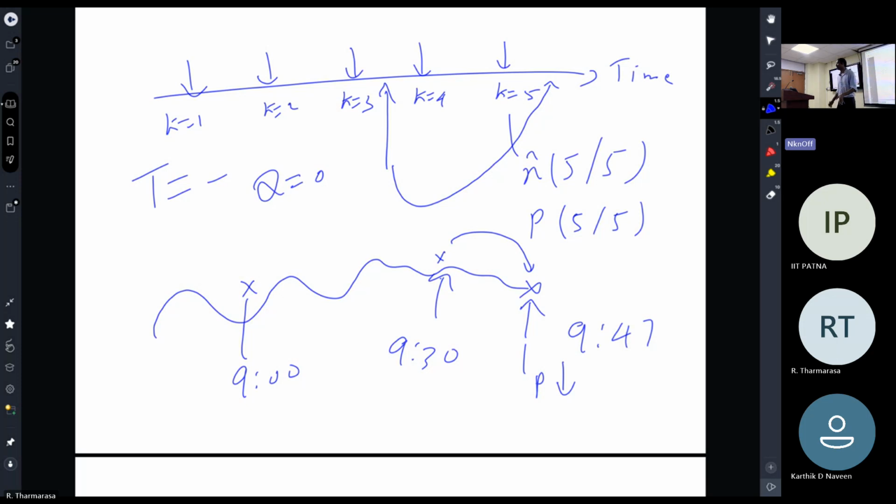Sometimes I think, because if I show the out-of-sequence measurement update equation, that's complicated. So one simple solution might be to always throw it away. Because if this is going to happen rarely, like say if you have 1,000 time steps and this happens only 2-3 times, then throwing it away is fine. But you can't do it either way: you have to update using the proper out-of-sequence measurement update or throw it away. By throwing it away, you lose some information, that's still okay. Okay? So that is the out-of-sequence measurement.